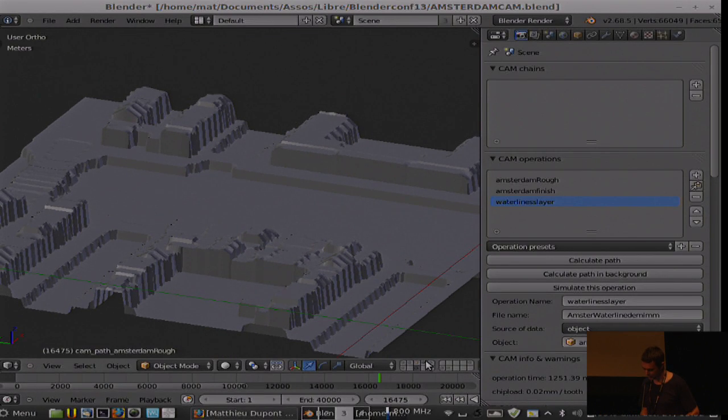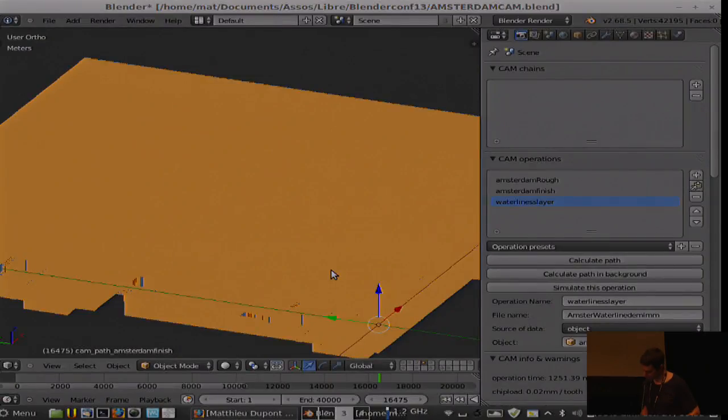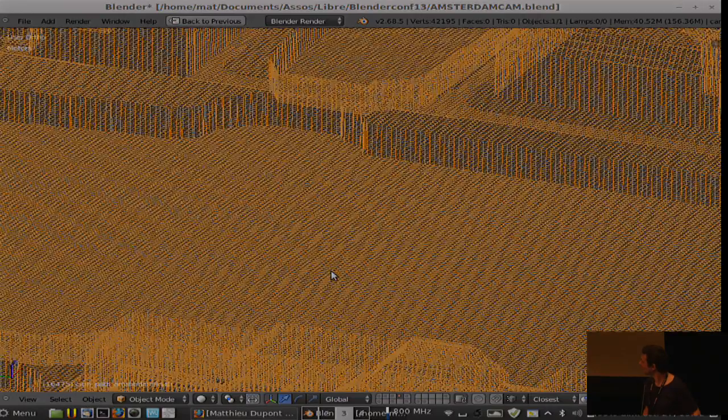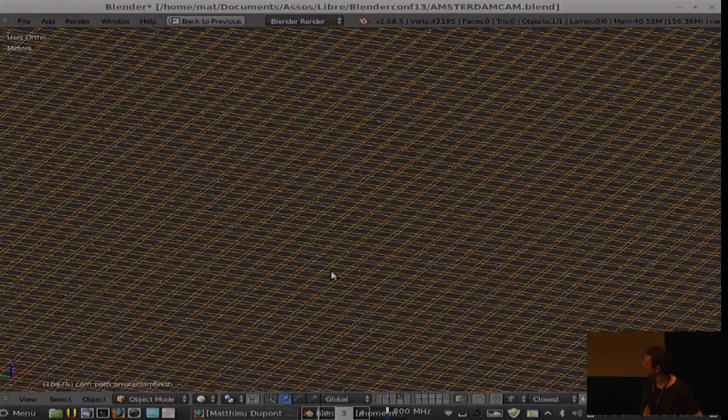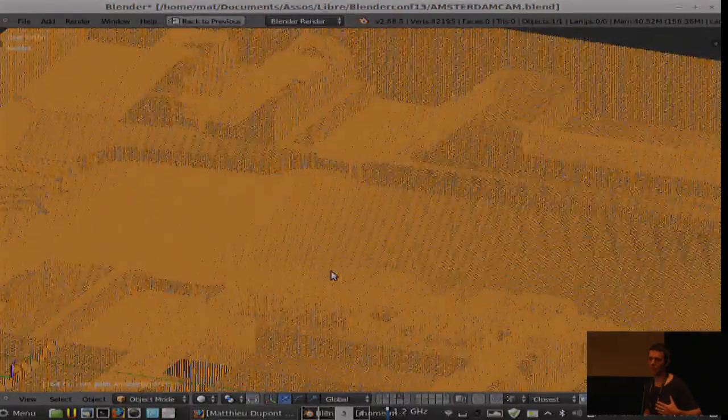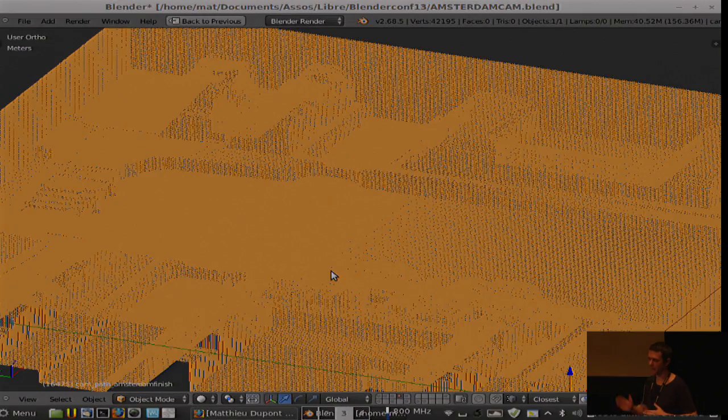Generally you know that with an 8 millimeter drill it won't be enough. And then you generate the second, I will put full screen because this is the finishing path. So here you have a lot of options. This one is in 2 ways, so it will mill first vertically in the y-axis, and then a second pass in the x-axis, so that you have a nice finishing.